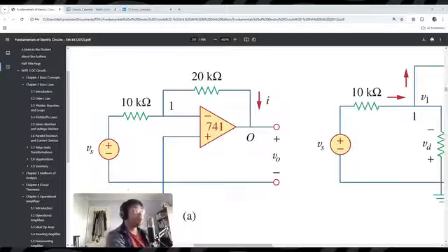So we could do a dot operating point, except it doesn't make sense because this is more of an AC signal, alternating current versus DC. DC would make sense if it were all resistors and no op amp. You could do the DC operating point for this node over here and this node. Although we're going to do nodal analysis with hand calculations afterwards.